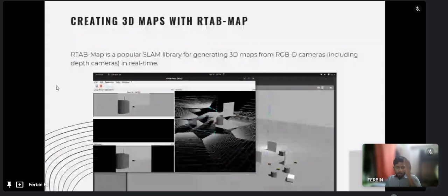To automate these tasks, the idea we came up with was using a depth camera to map the whole area of our ship. Once we have the map of the whole area, we have the reference, or the CAD model, of how our ship looks. Once you have the map of the object, we have a three-dimensional coordinate system, or 3D point cloud. A point cloud is every point, every coordinate of our object or our location.